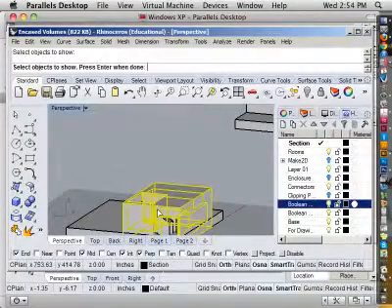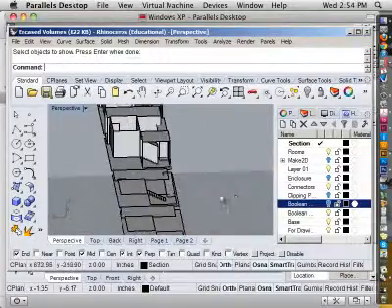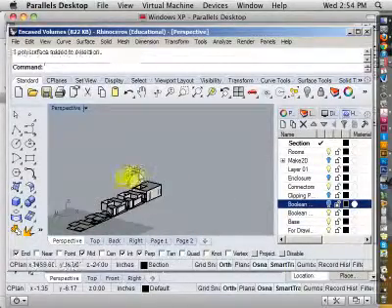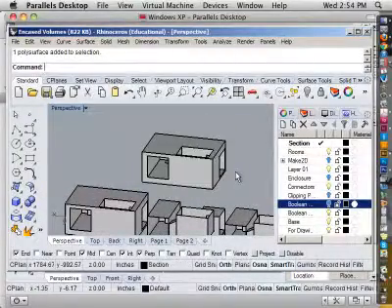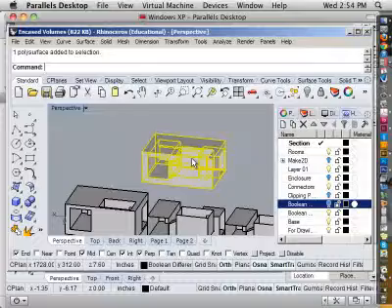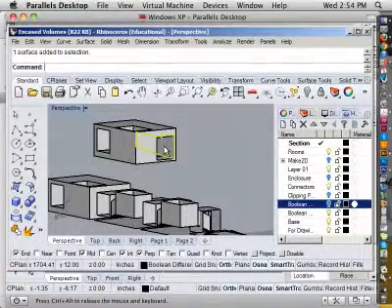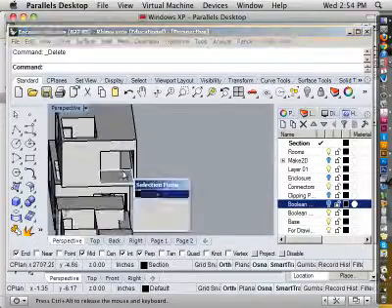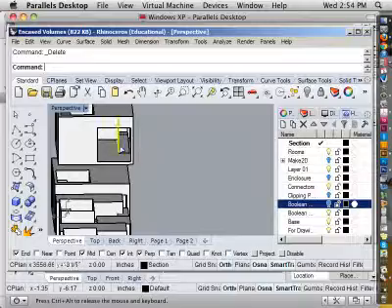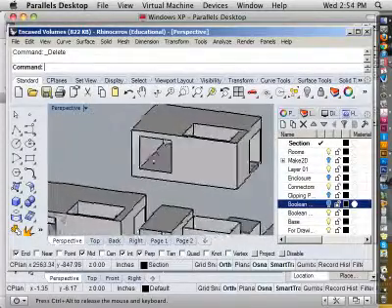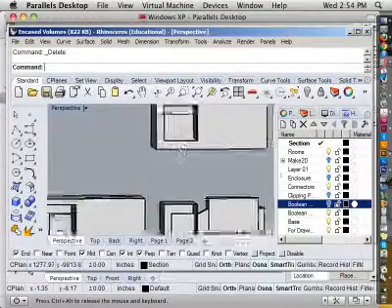So let's assume that I don't have any versions of the model where I have what I need for that option. You can select this Boolean version and explode, and you can manually go in and delete out the interior volumes that you don't need. For something that's a fairly simple design like you guys have, I think that shouldn't be too time consuming.